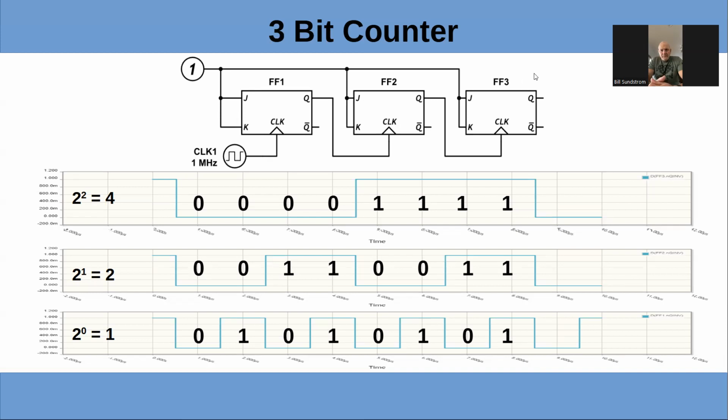Because in the real world, there's many nanoseconds delay between this one and this one and this one. The change is when the clock output goes to 1. The first one, when the Q becomes 0, it doesn't trigger number 2 until it goes back to 1 again. That's how it gets to the 3. Because each clock toggles it on a rising edge. So you have to have a positive going pulse in order to toggle each one of these.